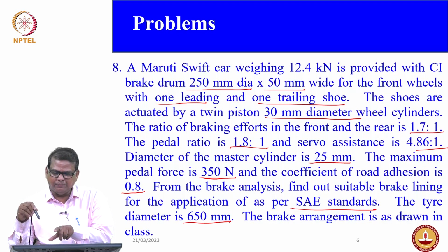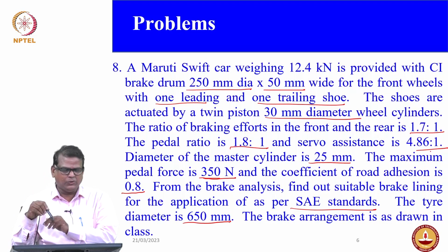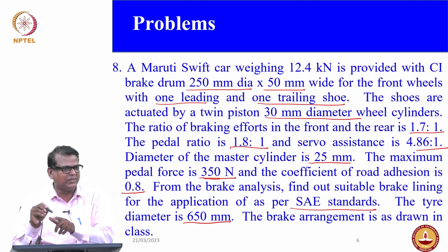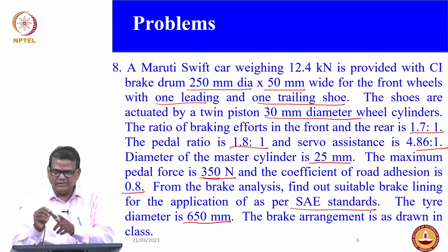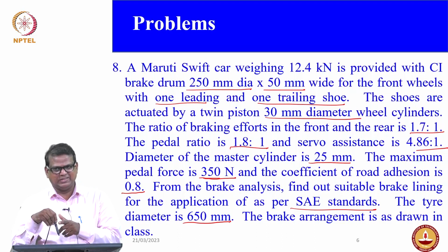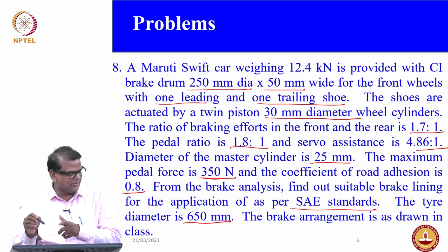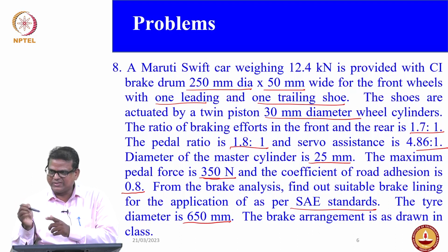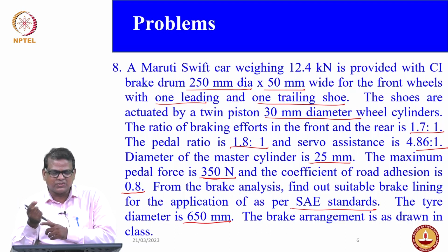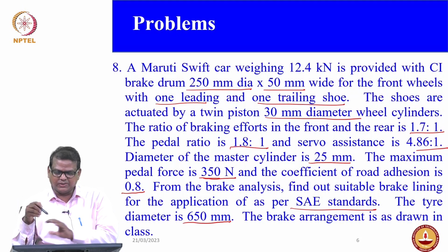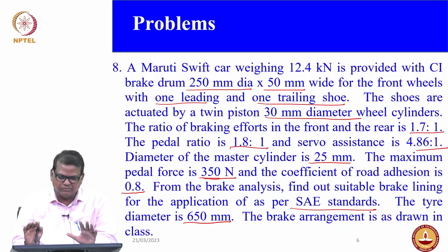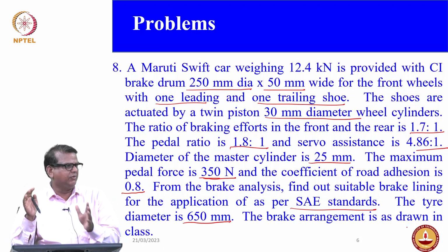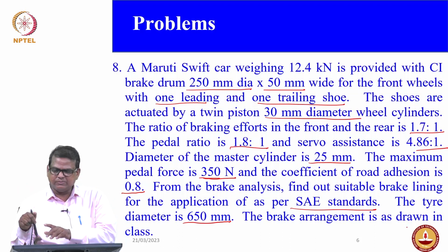So, that is the way it happens from pedal to lever to vacuum booster, where it goes to the master cylinder, right. From the master cylinder it should finally reach the wheel cylinder. The master cylinder and wheel cylinder are given in terms of diameter. And within that, the braking proportion of the vehicle is not given as information, but the proportion is given. Your KB front axle and KB rear axle proportion is given.